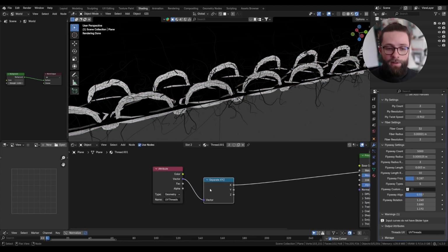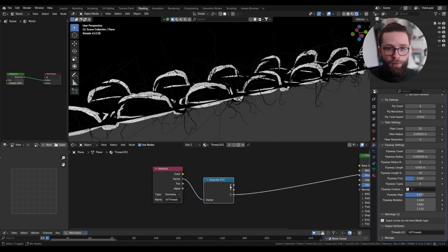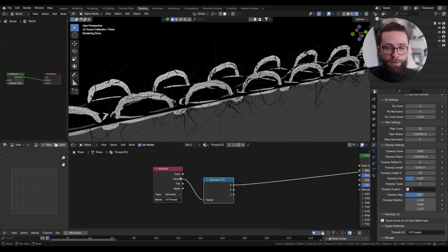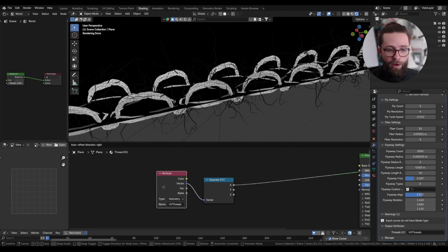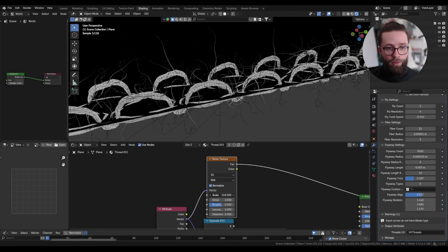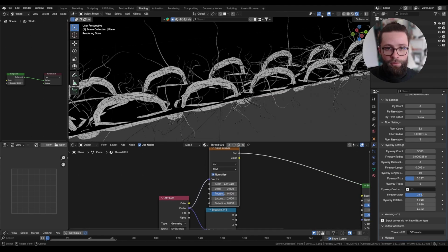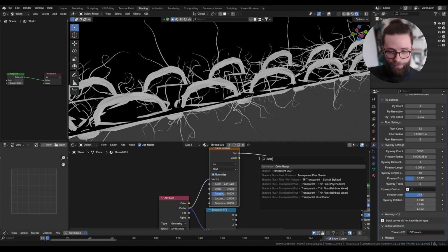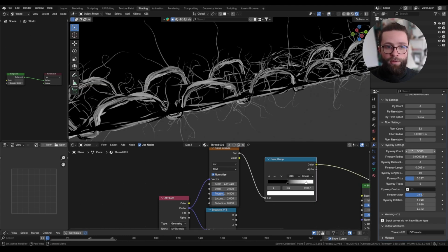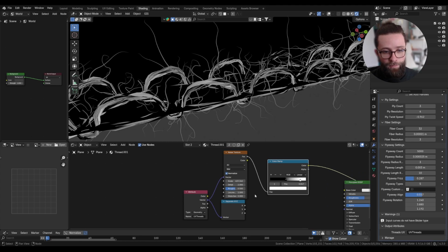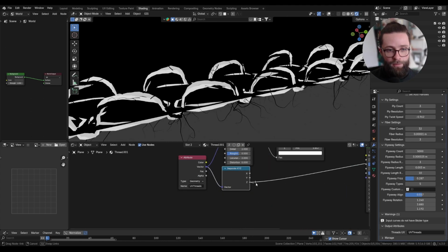So here, as in the other tools of the toolbox, it is not exactly a UV map with only X and Y coordinates, but I also store some data on the Z-axis, which is why we have to use the attribute node instead of the UV map node. But generally the first 2 coordinates are just the UV map of the curve, which can be used to drive a noise value like in this case, to improve the detail of the thread without having to use subfibers and so on. But the last value on the Z-axis is actually an index for the different ply of the fiber.